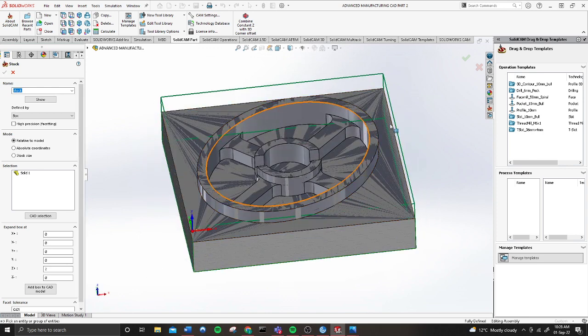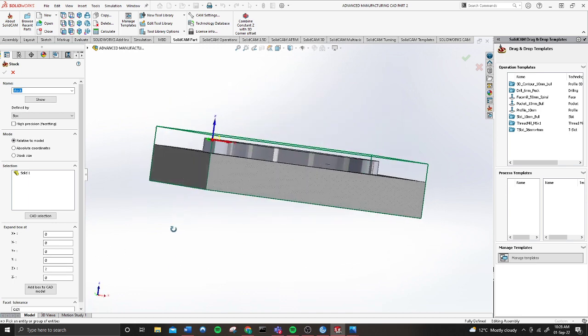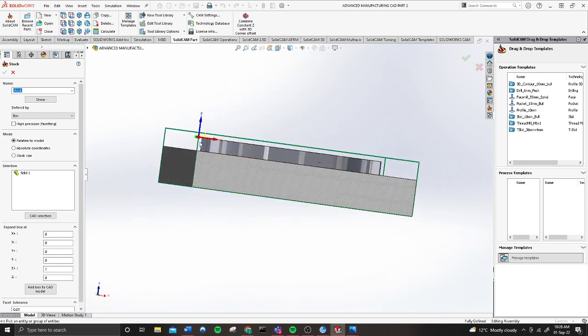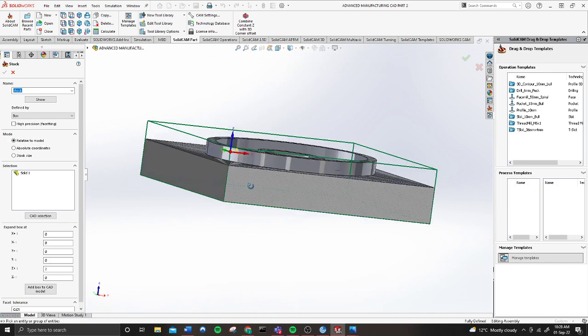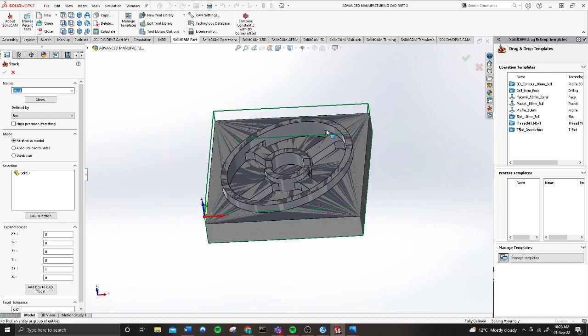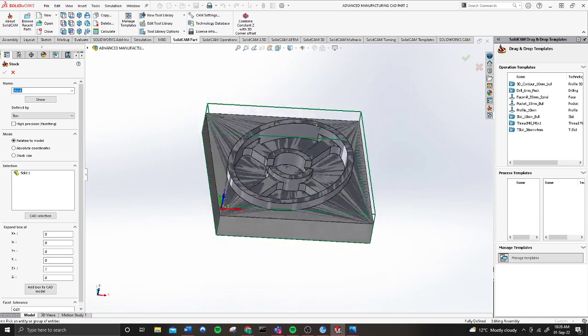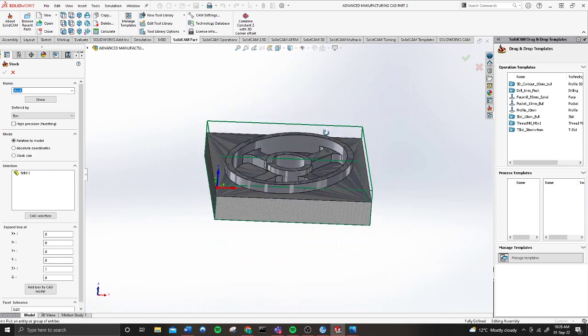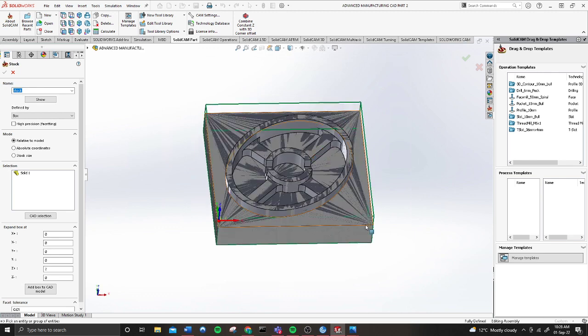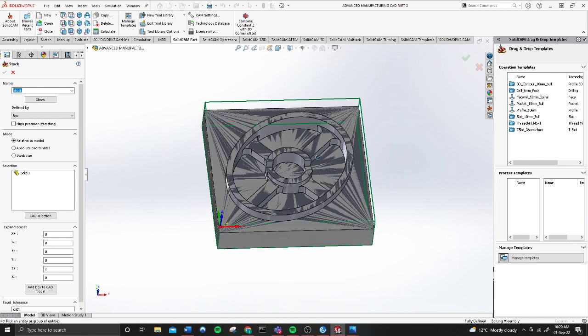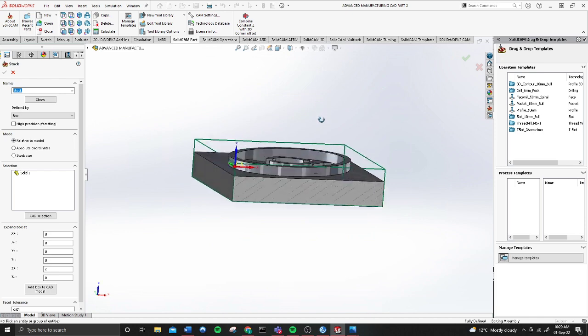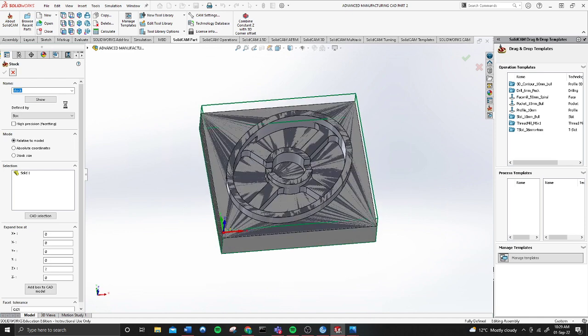So I've set 0 as all my edge coordinates, and then I've given a 2mm on the Z axis just because the drawing doesn't really specify what are critical tolerances, internal and external, so I've just assumed that the edge tolerances can be relatively close and then the internals are the accurate ones. So I've just specified the Z axis to give extra material.